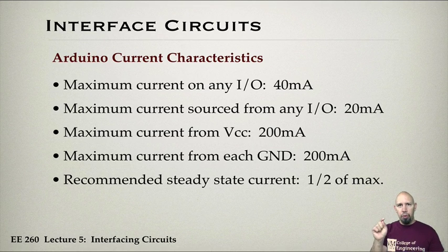For example, if you have digital pin 3 and you set it high, so that it's 5 volts, and you now short that to ground, then you've attached a 0 resistance across from 5 volts to ground, which is going to allow potentially infinite current. Well, obviously it's not going to be infinite, but it's going to be enough to fry that pin. So obviously that's not a good plan.